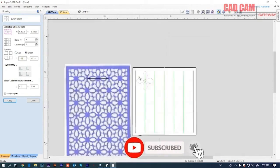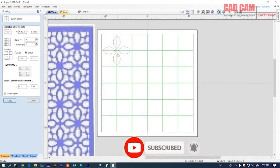This object that we just looked at here, if I zoom in a bit, when we selected this object, its size came up as 6.5 here. I set its row to 4 columns. And similarly, instead of a gap, I provided offset values. That is, the offset value between one and the other will be 3.66 on the X side and 7.33 on the Y side. But in the negative, because we want to move it to the lower side, we have an option here with column displacement values.